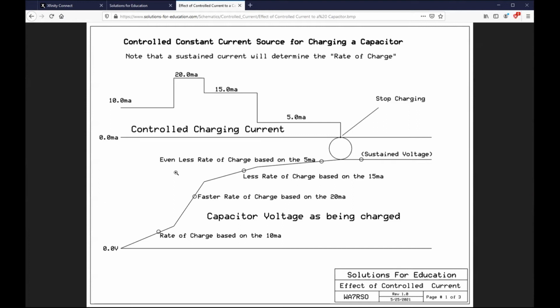All right. Let's say that somebody comes up with an ingenious method of making these two plates a micro-inch apart. Would you say that could substantially raise the capacitance, except you have a very low voltage tolerance before you have arc over? Sounds like electrolytic capacitors. As a matter of fact, that's where we're heading. Now, how do we do that?